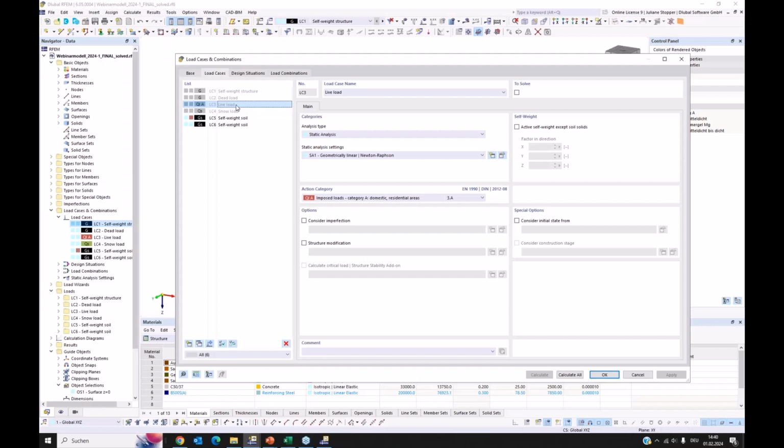There it would use the stiffness from 0 because we don't have other stress there, and this doesn't make sense. Before the live load is assigned and causes deformations, we already have self-weight of soil there, we have self-weight of structure there, and eventually dead load, and they all cause stress. From that the correct stiffness comes, and with this stiffness the live load should be calculated.